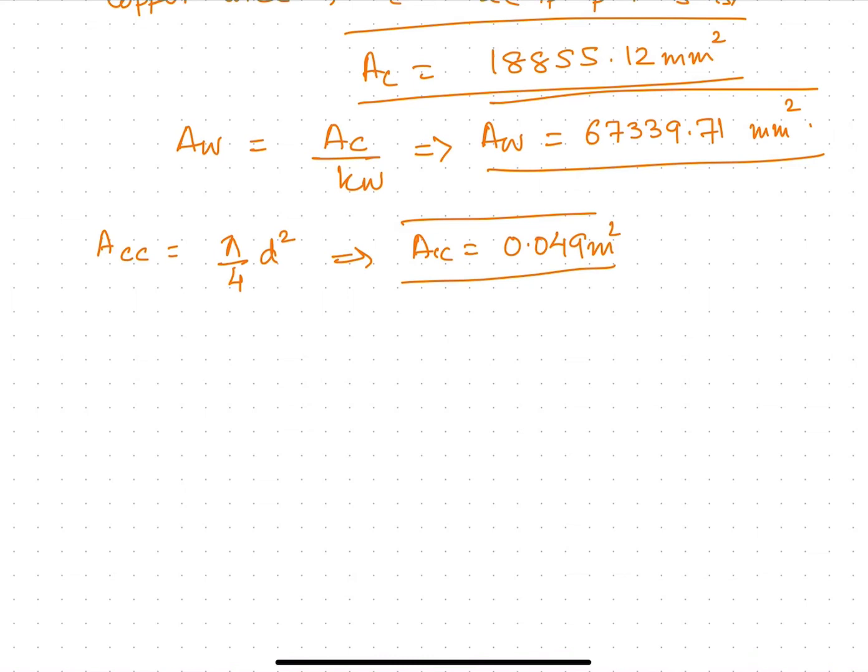Now also you have to calculate the gross iron area, and here we make an assumption, not an assumption, but we know from the knowledge of multi-stepped cores that this AGI, the gross iron area, is equal to 0.84 times the area of the circumscribing circle. You get this expression while deriving the areas in the core derivation.